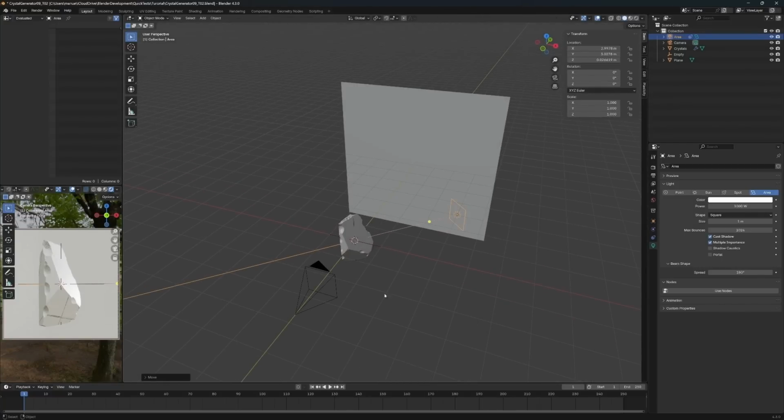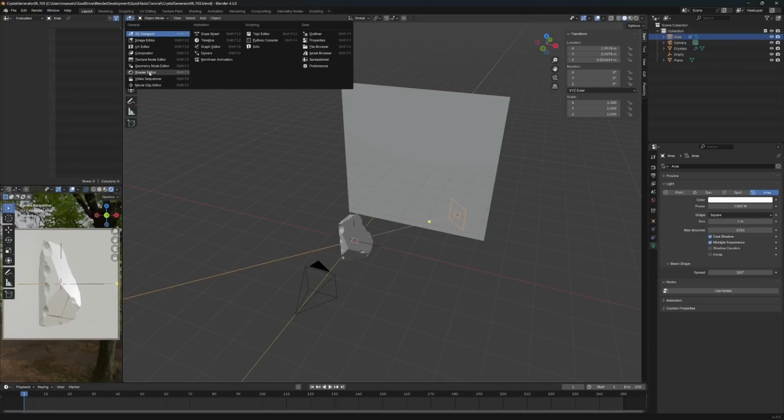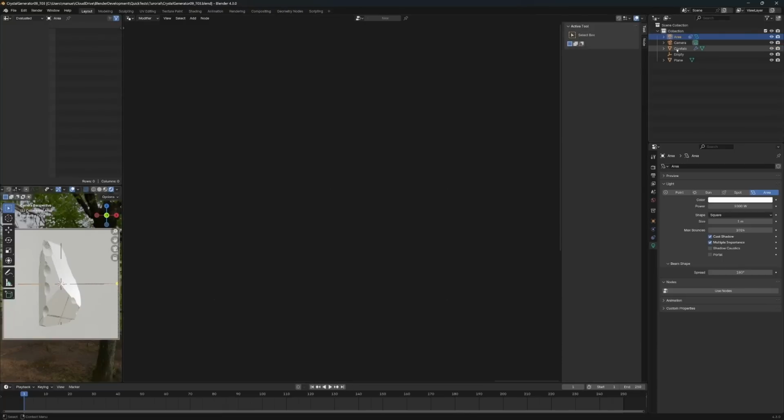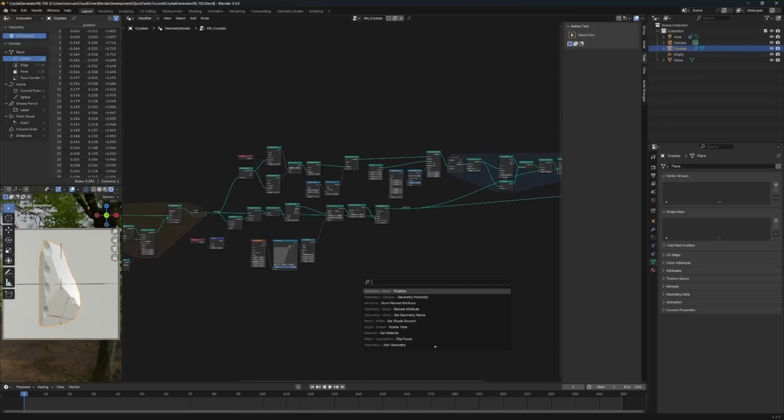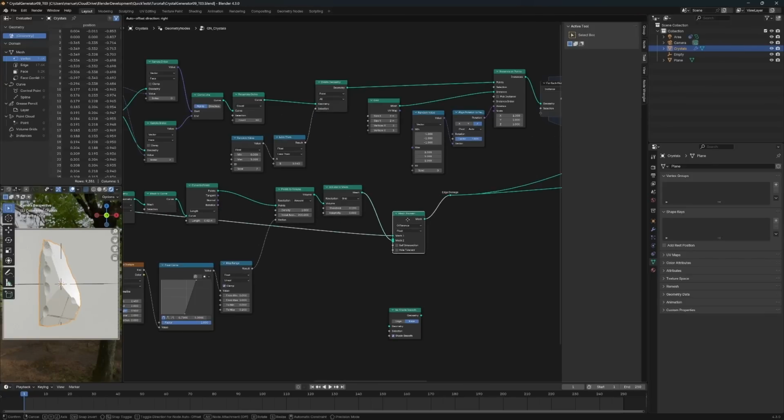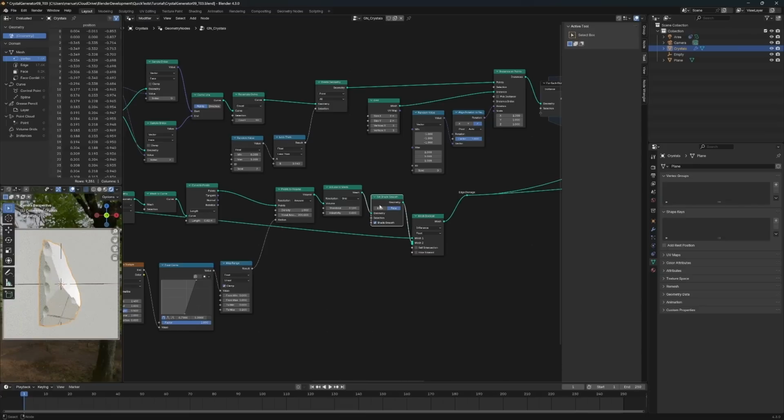Now let's try to create a nice shader for our object. For the shading, the very first thing I want to do is to go to the geometry node setup again and set shade smooth on the indented damage areas. For this I create a set shade smooth node, and I only want to use this node on the volume stuff.